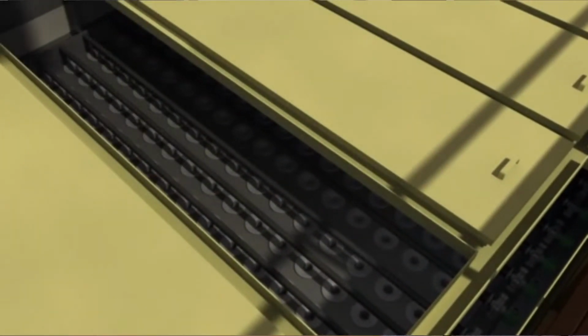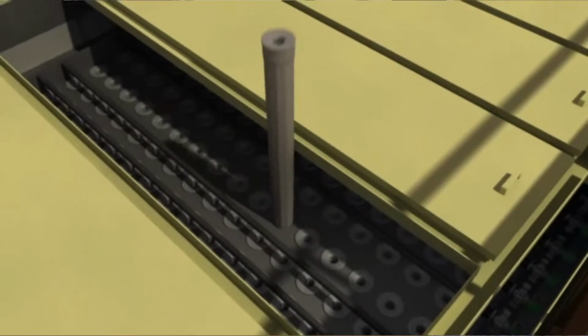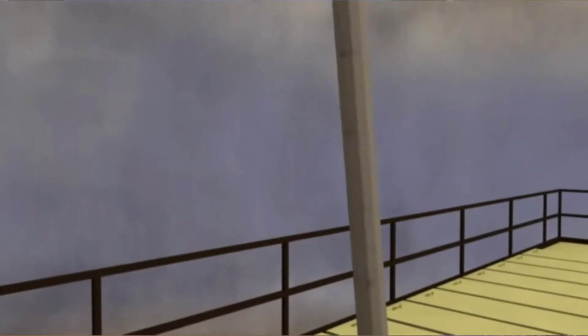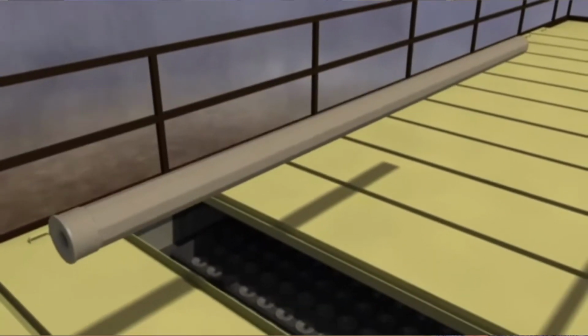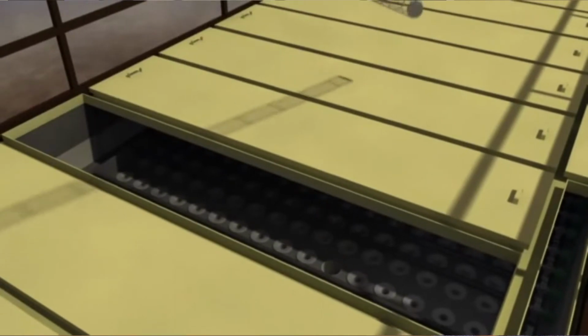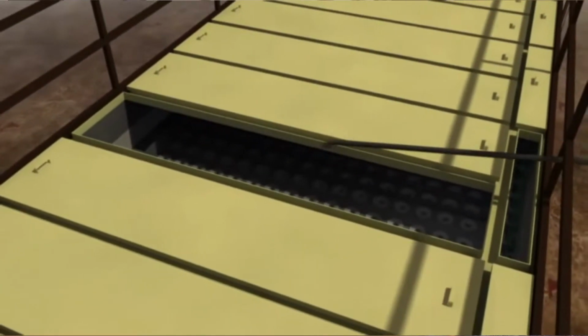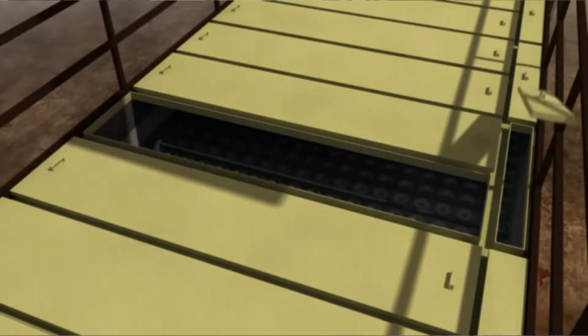Here's another view. If you remove the blowpipe and you can see the bags, this is something you would want to inspect when you're getting ready for a stack test. You want to see if you've got any dust on the top of that tube sheet. Just kind of a quick representation of how you would change a bag. Cage pops in, you would put your blowpipe back into place.